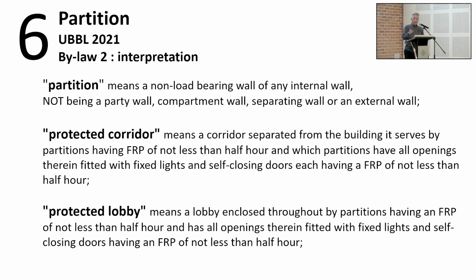Right, number 6, partitions. Partition means a non-load bearing wall or any internal wall, which is not a party wall, not a compartment wall, not a separating wall, and not an external wall. That means everything else. If the wall is not functioning as a party wall, a compartment wall, a separating wall or an external wall, then it's called a partition. Then you say, why am I having partitions in this fire safety seminar? Some partitions will actually need to be fire rated. So you say, where in the world?